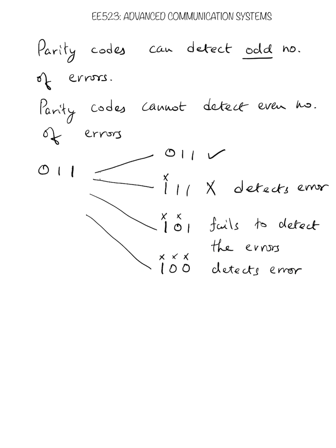And even if it can detect it, it cannot correct it because the coding scheme does not know which position has been corrupted, whether bit number 1, bit number 2, or bit number 3, because the receiver does not see what you transmitted. It only sees what it received. By looking at the received code word and following the rule that it has to be an even number of ones, it finds that the number of ones is not even, and therefore it knows that there is a problem.